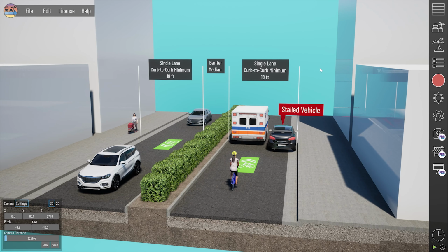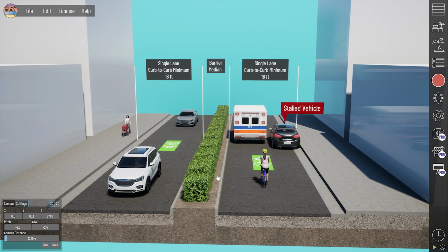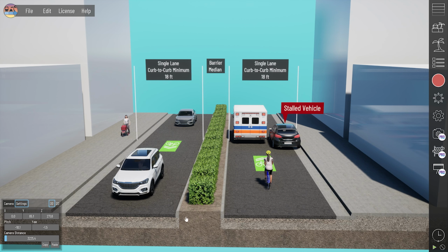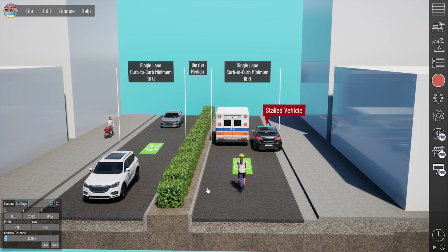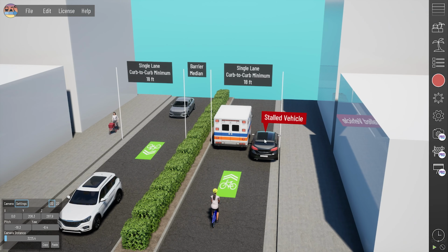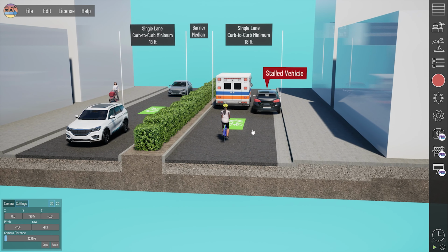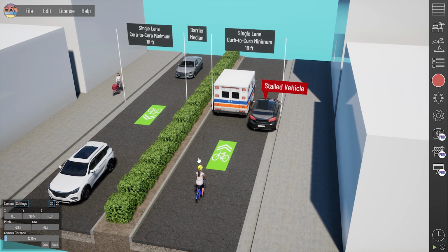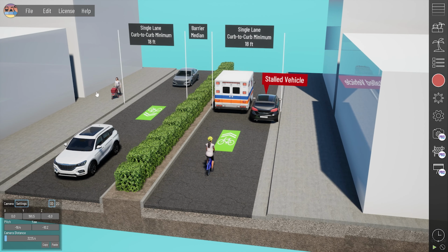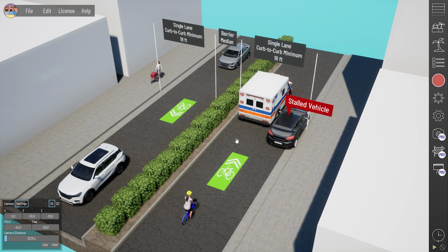This is the stalled vehicle lane clearance example project. This is one, again, I've encountered in my career where on certain roads with a desire for maybe a barrier median, there is probably a minimum physical clearance you would want to consider and provide in the case that there could be a stalled vehicle on that section with barriers on both sides, so that in a case of an emergency vehicle, there would be the physical width for those vehicles to clear that stalled vehicle and continue on down the road. You'll see here I've paused, actually turned off moving traffic because I've added some static assets,